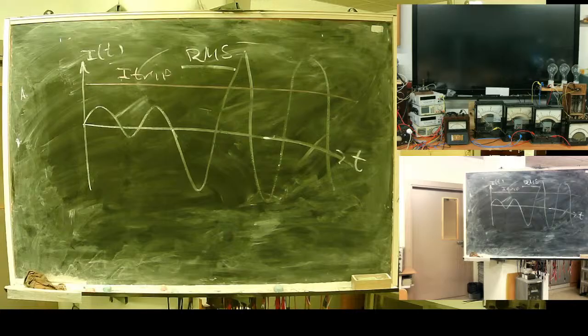For me, I am a customer. I'm ordering protective device. I would like it to be friendly to my knowledge. If I knew 1 kilowatt consumes 5 amps, 20% above, okay, 10 or 16 amps. I would like to disconnect line if current exceeds 16 amps. It's normal. It's the idea for a simple circuit breaker.